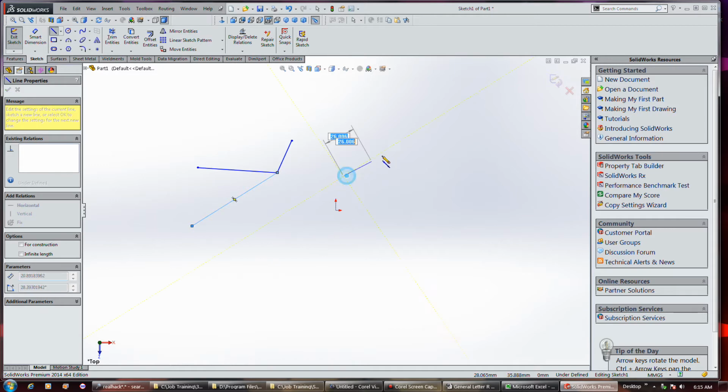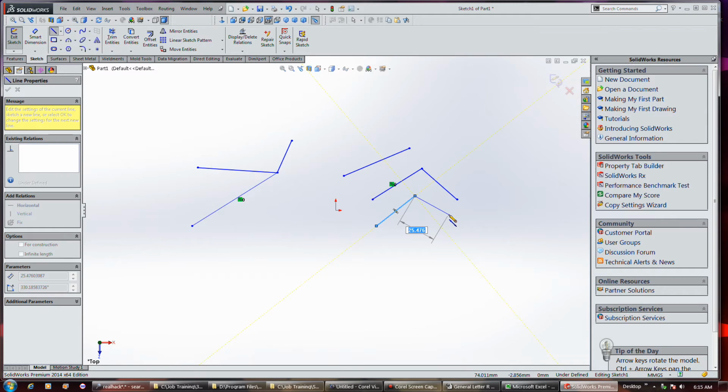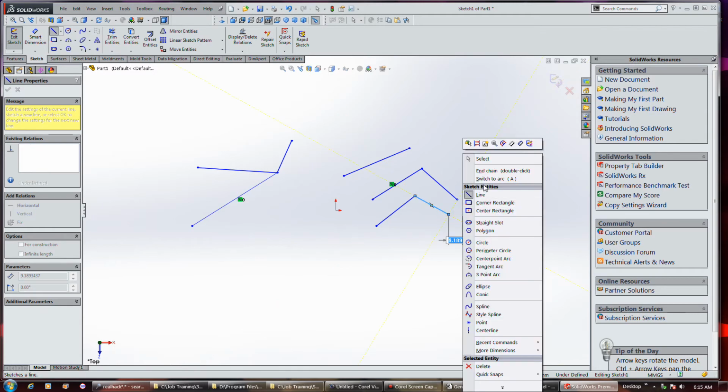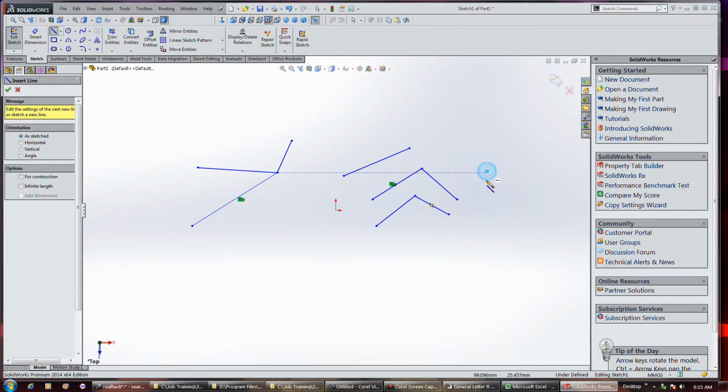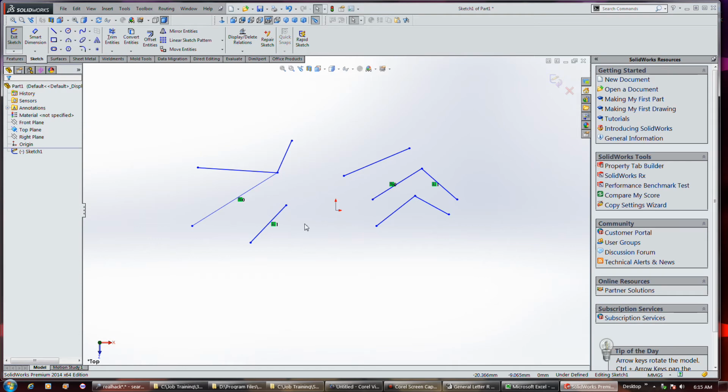But like I said, when you're clicking a line, you can chain them, and you stay in line mode. Double clicking is the only shortcut for that. Otherwise, you press the escape key, and you're screwed. Okay. And enter won't get you back into the line command, apparently.